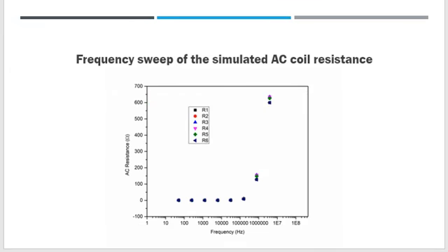The AC resistance showed an exponential increase once the frequency reaches 700 kHz and beyond, due to the skin and proximity effect. The induced eddy current causes non-uniform current distribution within the material and increases the cross-section resistance.